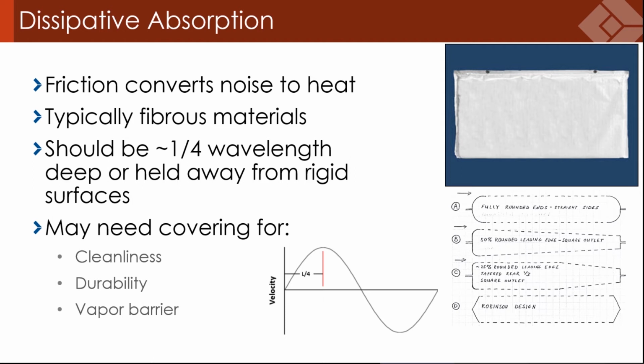But when you've got something like a fiberglass or a rock wool absorber, what's actually happening is the acoustics moves the fibers and they rub together and create friction and turn into heat. And it's really small amounts of heat, so don't count on heating your house that way. Although there are acoustic refrigerators now that I think Jerry and Tom's are using.